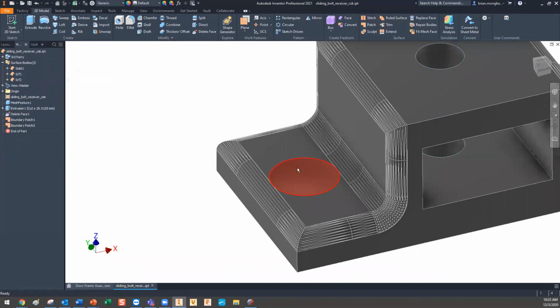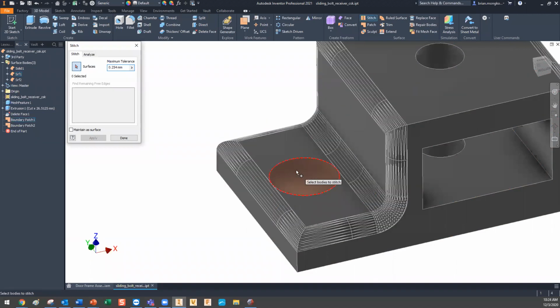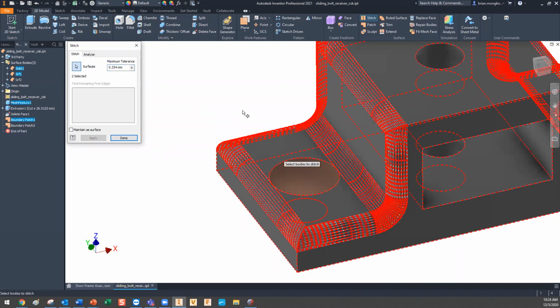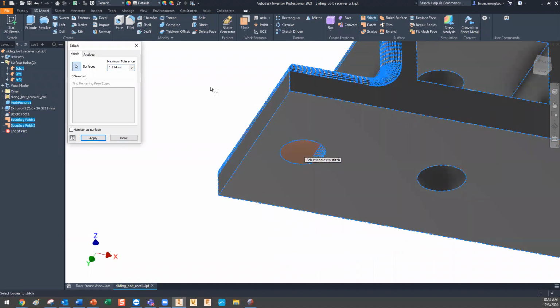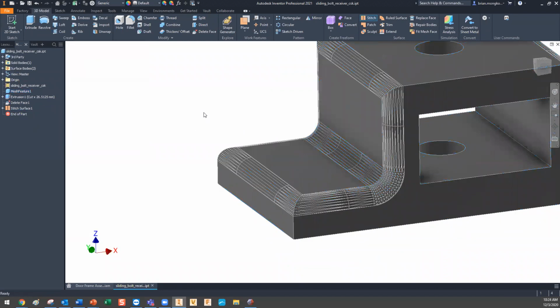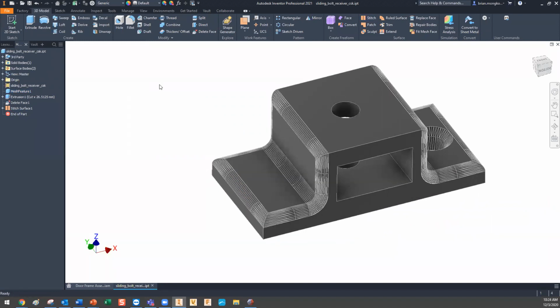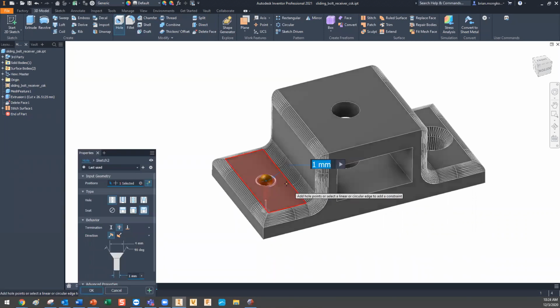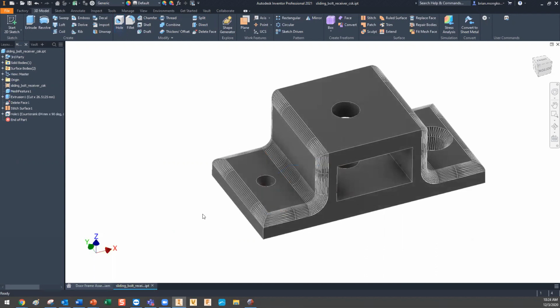Now it's not a solid body yet, it's still surface, and that's because these aren't what's called stitched together. And to do that, there is a stitching tool. So I can go ahead and select my 1, 2, and 3 surfaces to stitch together. And now it's a solid body. And the point of patching that together is so I can create my own hole tool at that location with whatever numbers that I want to put in for it.